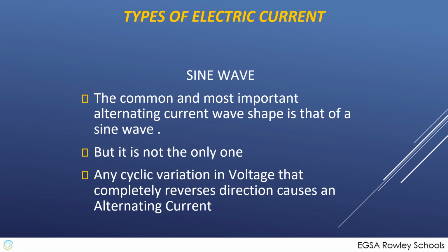When you're looking now at a lot of systems that are going to be adding solar and other DC power supplies and try to make them AC, not all power converters are created equal, and you will get things that are not pure sine waves. In fact, in some cases, you'll even get just flat out square waves. That's still alternating current as long as the actual polarity that you measure at the wires coming out switches back and forth.